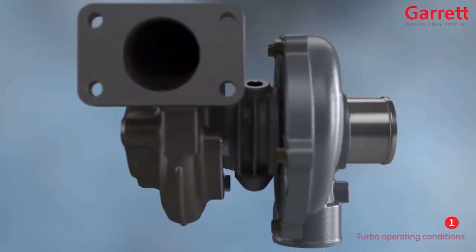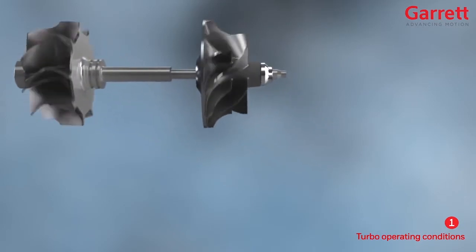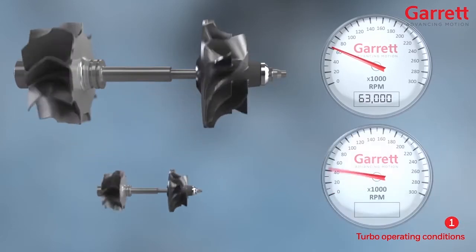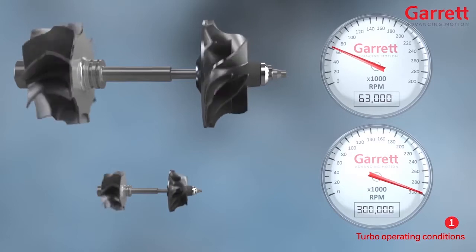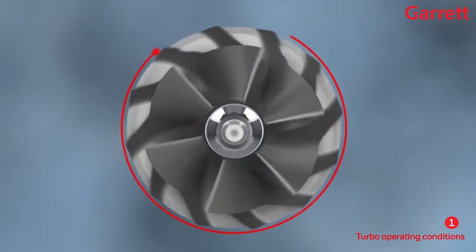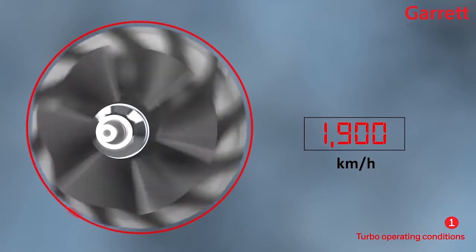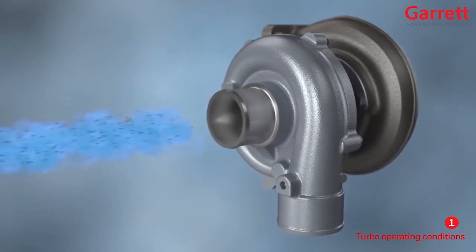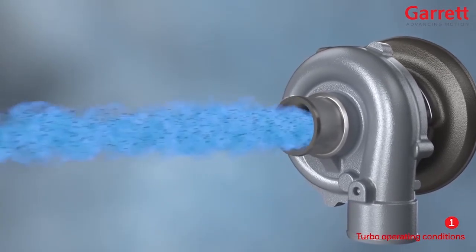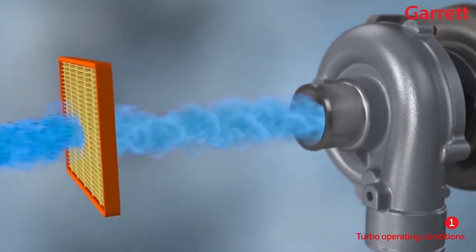The turbocharger runs at extremely high speeds for maximum efficiency. Our very largest turbo spins at up to 63,000 RPM, and the smallest rotate at more than 300,000 RPM. If we consider one point on the circumference of the wheel, when operating at full speed, that point is traveling at over 1900 kilometers per hour. This high speed of operation is why it is so important that the air is properly filtered before it enters the compressor, to avoid the possibility of foreign objects entering and causing catastrophic damage.